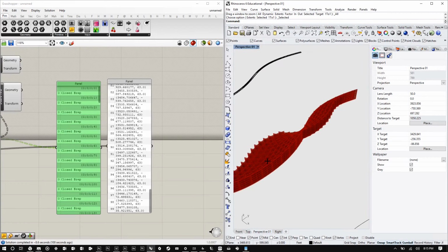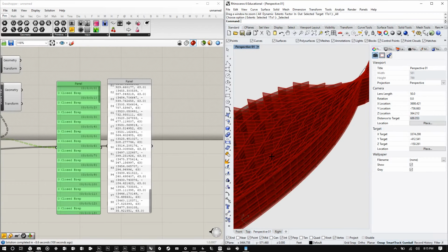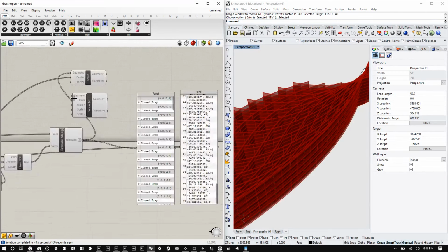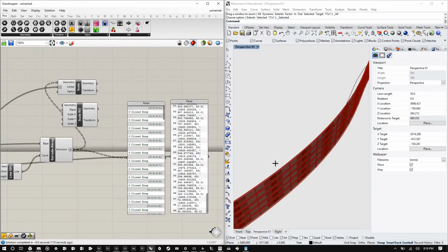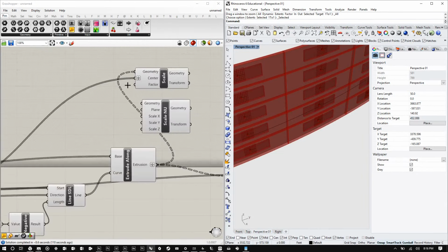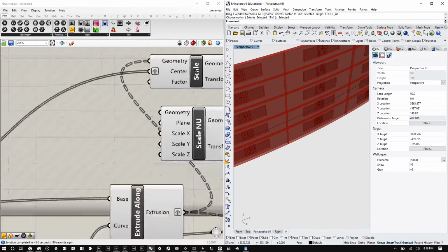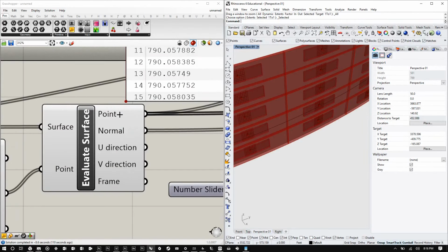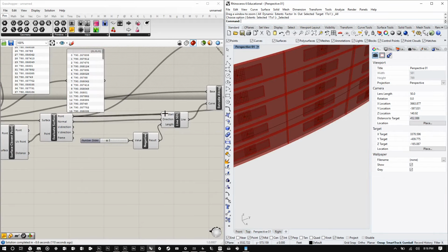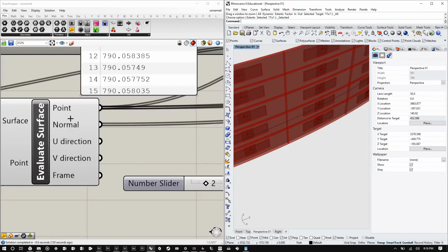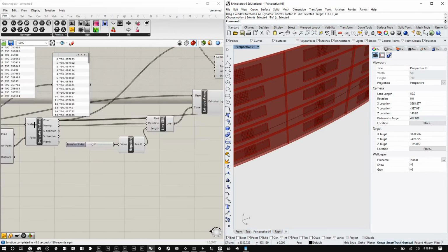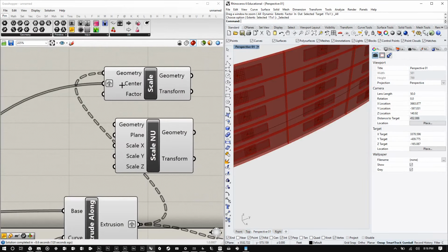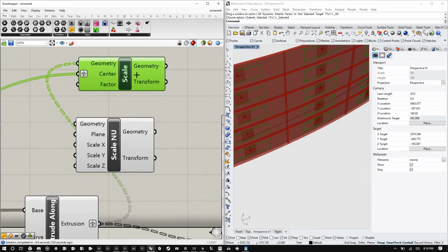And you can see that it's because it's scaling some of them on some points that are far away, it's done a really weird scaling thing. So that's not what we wanted. We wanted all of them to be grafted. So now the lists match. So I can either graft it here or graft the original over here. But because there are other commands that required it to not be grafted earlier, I didn't graft it here because it will then graft everything else after it. So you can pretty much graft the list wherever you want. But now these match, right?